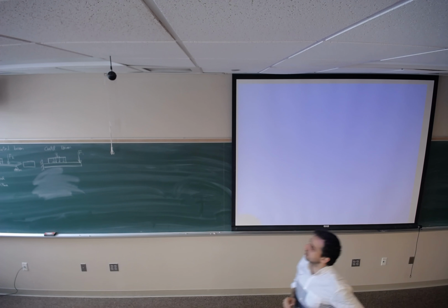After we find that section, for example, this is the section, which is representing the critical section. Then I'm going to look at the cross section here, which is going to be something like this. And then I will find the critical point. Which point of that critical section is going to see the failure first if it occurs. So critical section, then critical point.